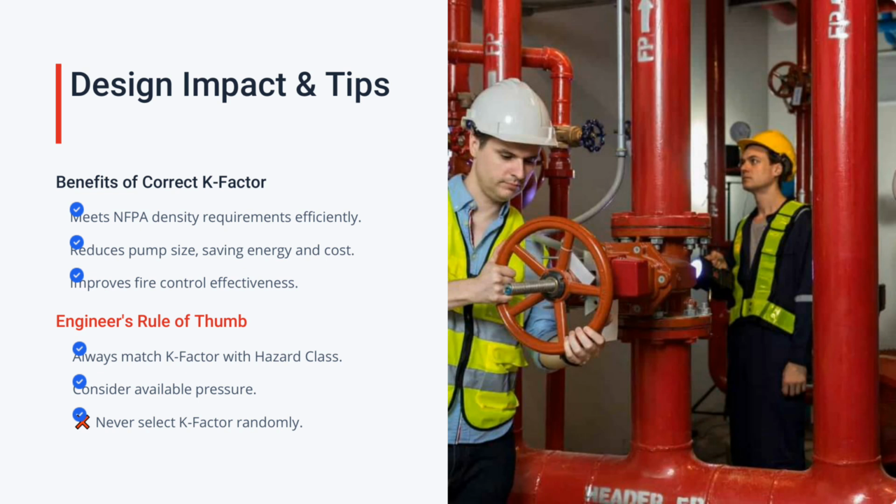The right K factor helps meet NFPA density requirements, reduces pump size, saves energy and cost, and ultimately improves fire control. Engineers tip: always match the K factor with the hazard classification, design density, and available pressure. Never select a K factor randomly. It can compromise system performance and safety.